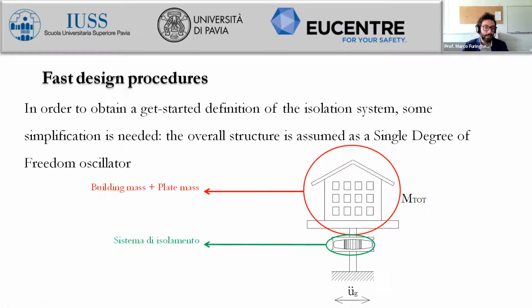This means that the overall assumptions and the results that we will get at the end of our design rules will be checked afterwards with specific and detailed analysis, for instance, nonlinear time history analysis. This is what we are going to do next week with SAP 2000. But at this moment, we just need to start with the design of the single devices.